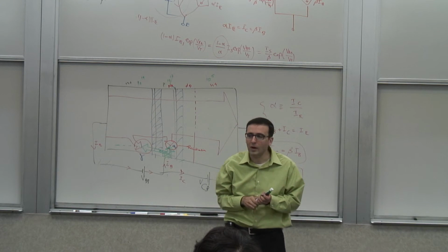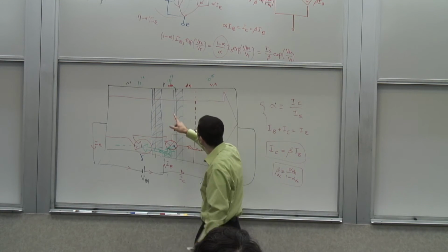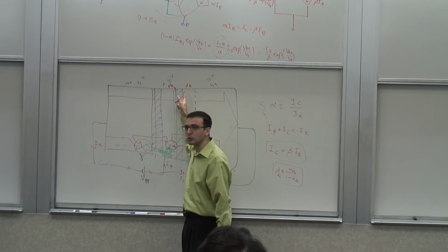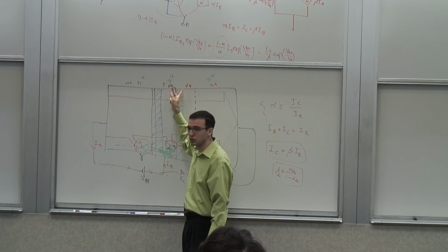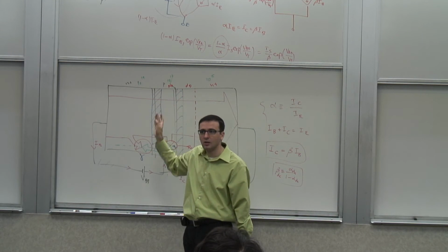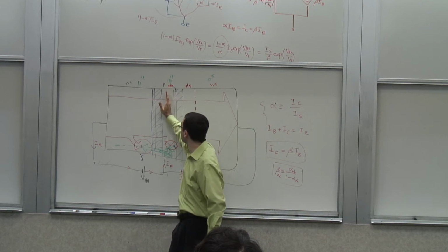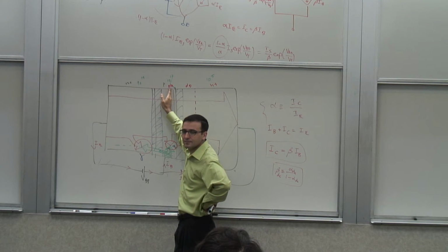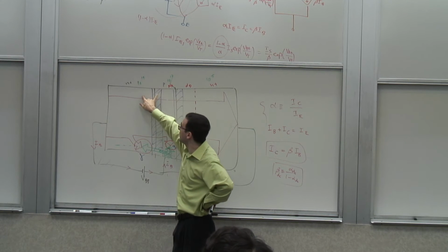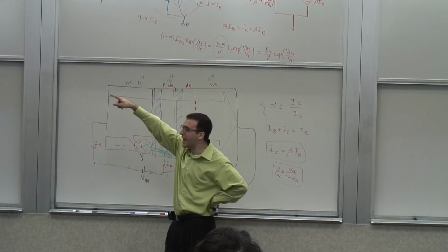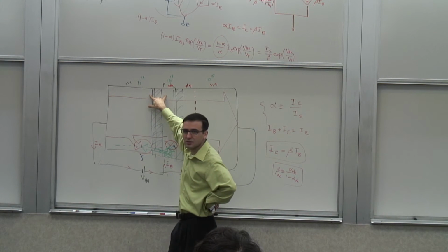What if I could somehow increase my NA? I could increase my ND too, and keep the ratio constant, because I want the ratio to be large. But what does that conflict with? If I increase my NA, it will lower my emitter injection efficiency. And the recombination, but it's primarily injection efficiency.